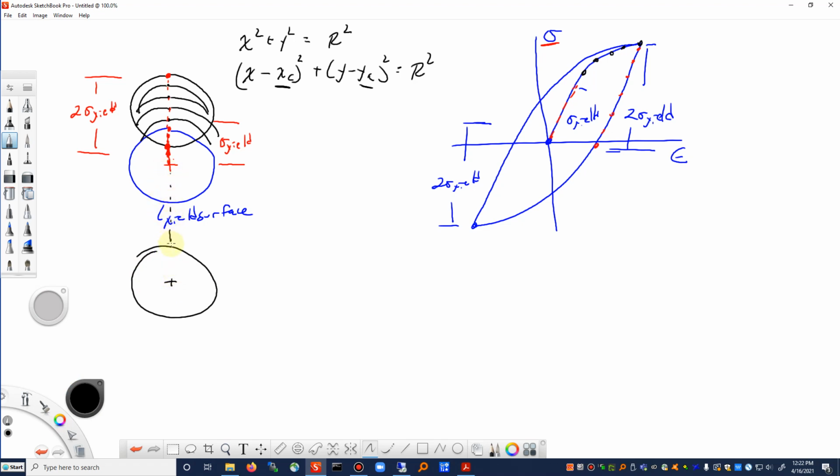Okay, so it goes all the way down to here. This point that was at this spot is now down here, and that's where we are down at the bottom of this, and then we just repeat this loading over and over again, and we recreate what we observe in uniaxial behavior. Now the power of this yield surface is that we're no longer restricted to just uniaxial behavior. If we have multi-axial stresses, we have different combinations. We can take this surface and drag it off at any angle that we want. We can go around here, we can unload it, we can go over there. We can do all kinds of interesting paths to calculate what our plastic strains are.